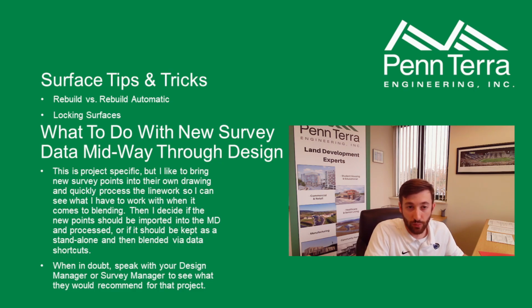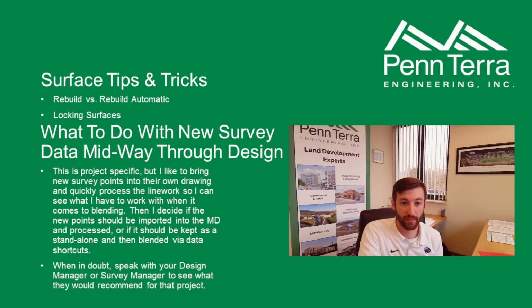I'm going to show you rebuild versus rebuild automatic, which can keep your drawing from freezing up and crashing depending on what you're doing. And then locking surfaces, which is good for preserving data, especially on existing surfaces. And it can prevent you from accidentally messing something up without knowing, which can be easy to do.